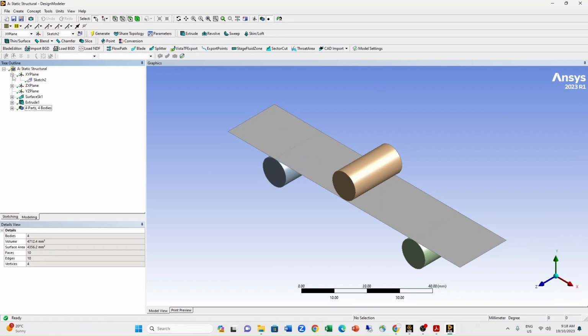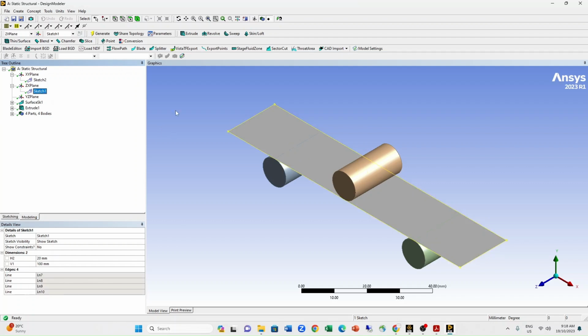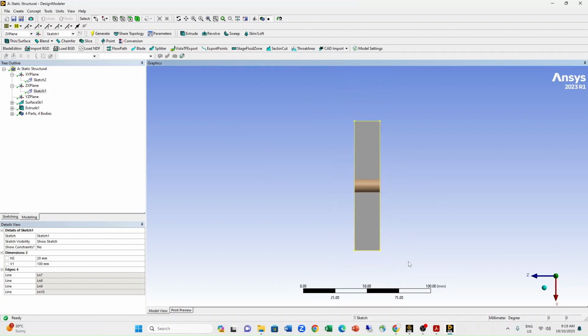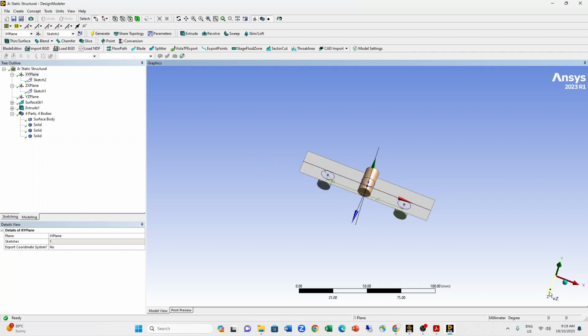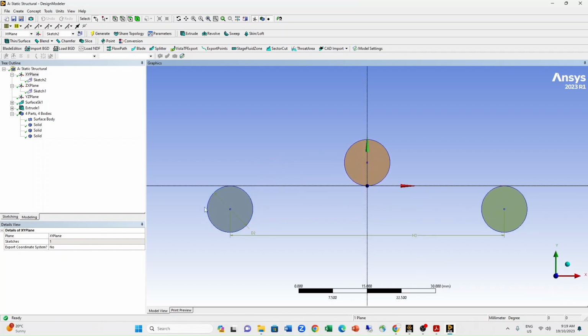So in geometry, the aluminum plate is actually being modeled as a 2D shell structure. For sketch 1, that is actually the sketch. Basically from the sketch, a rectangle, we can create a surface body. And secondly, we model two supports and one loading node.